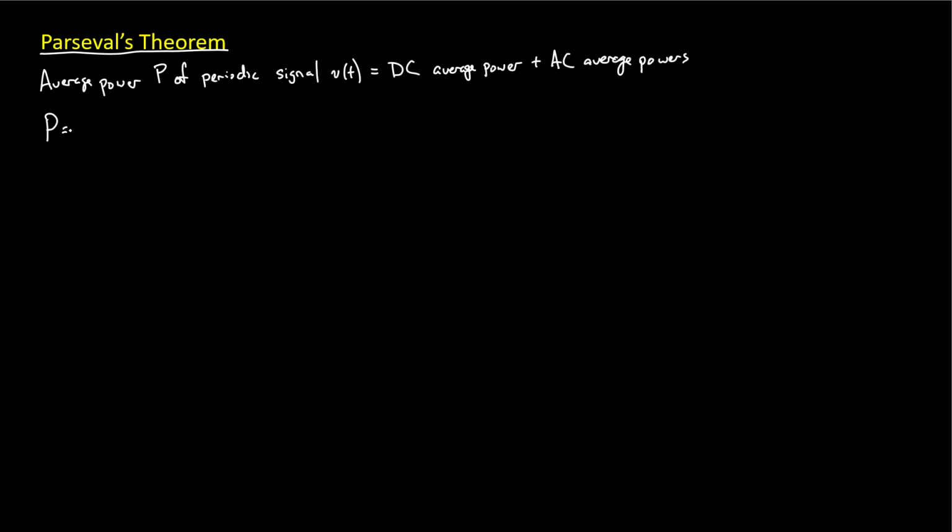The power P, you already know that if you've got that signal, the same signal, V of t, if you find its RMS voltage and you square it, then that's the same thing as capital P. That's the same thing as average power. You work this out in signals too. In fact, that was really the definition of what VRMS was, the equivalent DC voltage that would have to be in order to have the voltage signal produce the exact same power. And in our last online lecture, I pointed out that that's also equal to this formula.